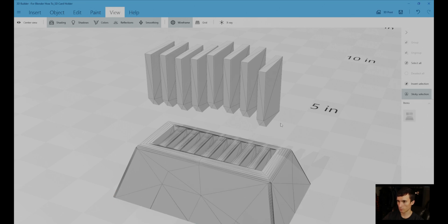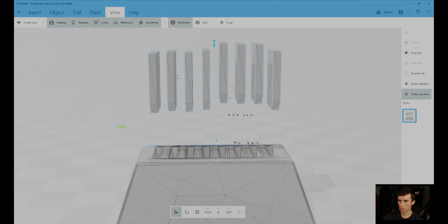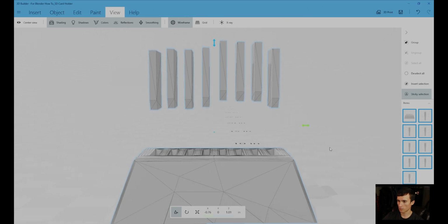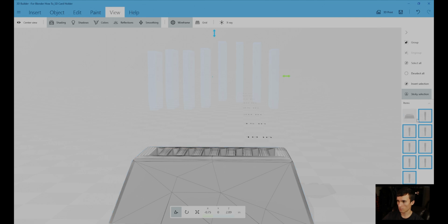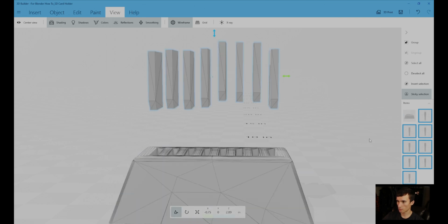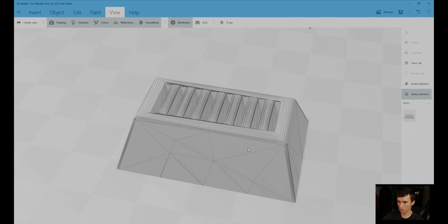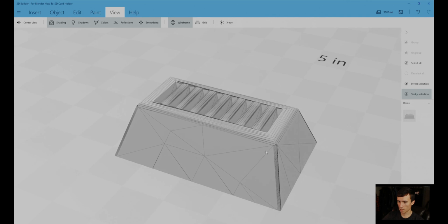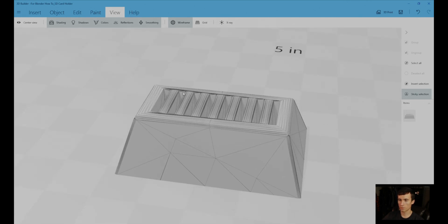And that did it fairly quickly. And I don't need all these SD card models, so I'm going to select them. Or let's select this and ungroup it first, because it's thinking it's all one object. And now we could select everything, all these SD cards, delete them, and it's repaired. And at this point, this mesh is suitable for use in Ultimaker Cura.